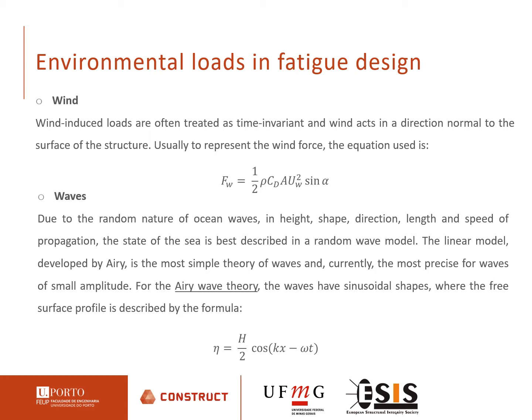Waves. Due to the random nature of the ocean waves in height, shape, direction, length, and speed of propagation, the state of the sea is best described by a random wave model. The linear model, developed by Airy, is the simplest theory of waves and currently the most precise for waves of small amplitude. For the Airy wave theory, the waves have sinusoidal shapes, where the free surface profile is described by the formula below.